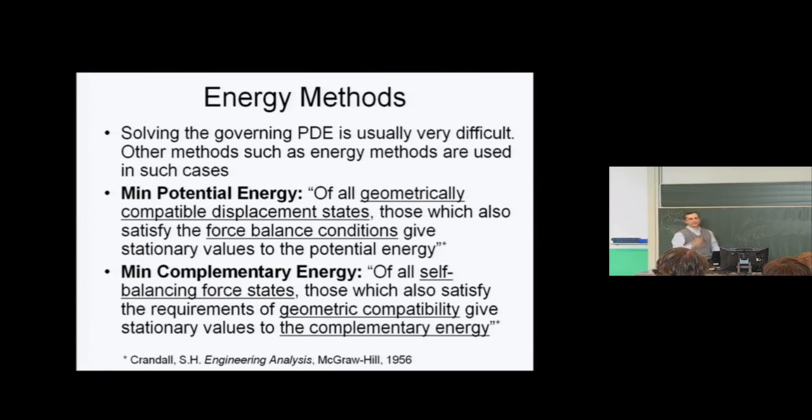satisfy the strain compatibility. Now, all this sounds like philosophy and relatively boring, but it's the basis of all good approximate methods we have. Finite elements are based on this. The methods we'll be talking about here are based on this. And recognizing what you assume and what you satisfy is important, because sometimes you will get incompatible results and you don't know why.